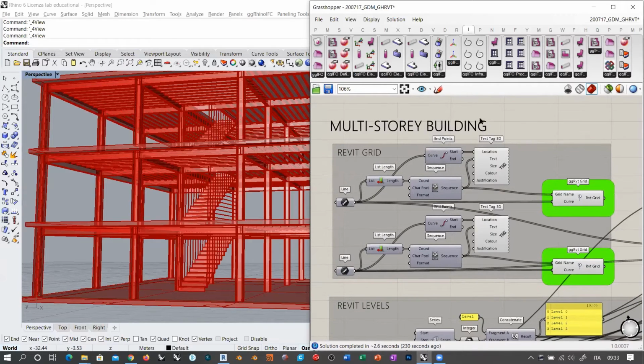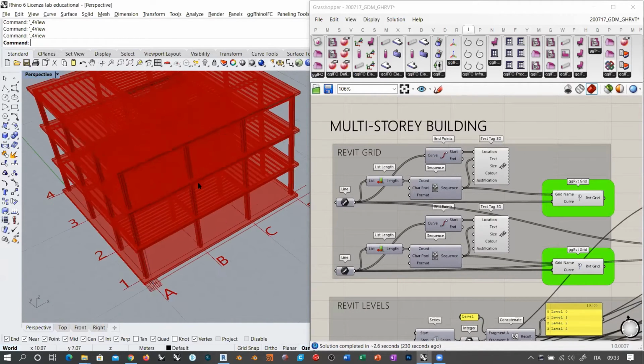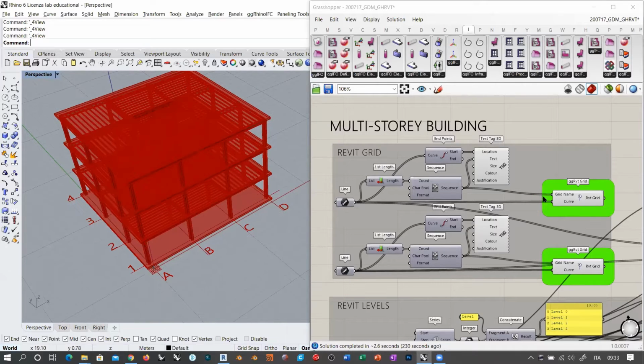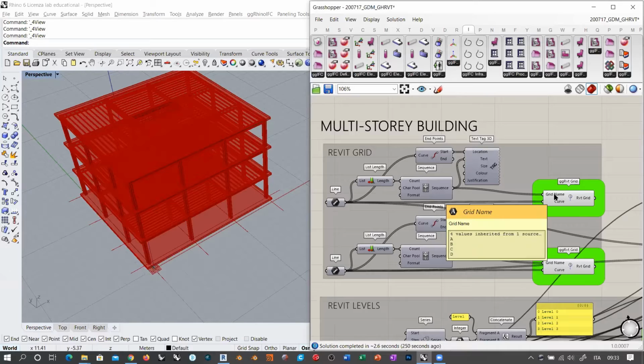Of course, we have some grid lines, which is some basic stuff. I'm not going to go through this anymore. Just remember that this tag asks for visualization here in Grasshopper, but you don't need them actually. Also remember one thing, which can be important. The labels that you are plugging in here, so the grid names, follow the sequence order.